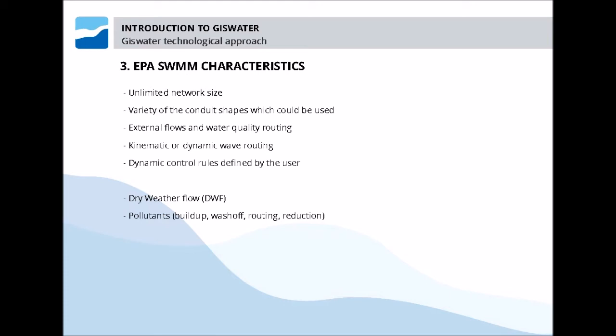It is necessary to point out that the model of pollutants is very difficult to use since it is very hard to calibrate, whereby a model of pollutants in SWMM will only make sense if we are able to calibrate those results. And that's a complicated task, but it does not matter because if we remained only with normal volume flow and rainwater flow, it is a calculation model perfectly valid to calculate all our networks.